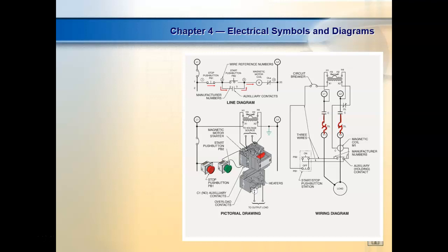Overloads more and more are moving to solid state overloads. So on a heater overload, if you change motors or if you change currents, you'd have to change the heaters. Solid state overloads, you got a little dial on there that you can turn, which is also in itself dangerous. I don't like it. So what would happen is a motor kicks this overload, and what's the guy going to do?